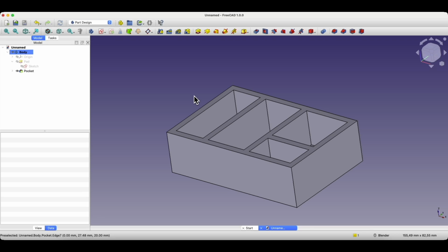Currently, slicers support the STEP format, and I feel that this is a better format for exporting files because the STL format is a mesh of triangles. When it comes to making any edits to such a triangle mesh, it is quite a cumbersome process. The STEP format is a format in which the solid is saved. When it comes to editing such a solid, it is much easier than editing a model that is saved in an STL file, so if your slicer supports STEP files, and usually slicers used for hobbyist 3D printing support the STEP format, I suggest exporting models to this format.